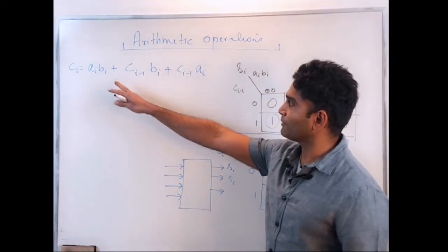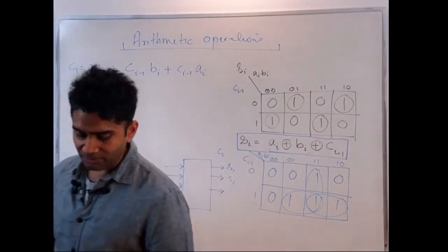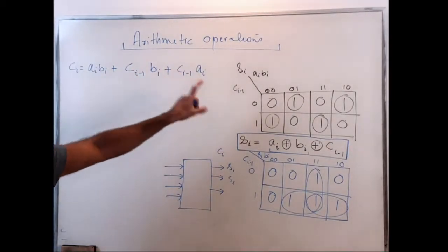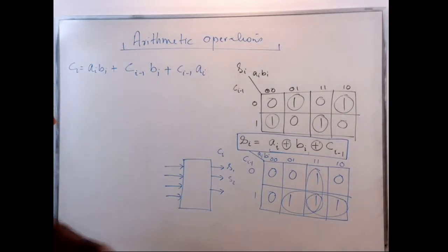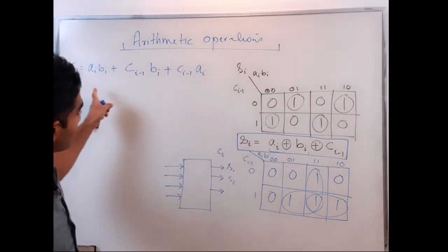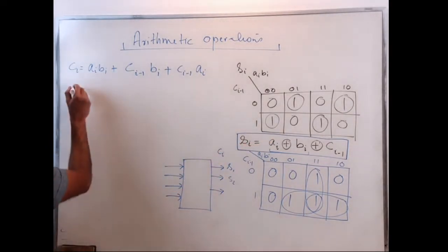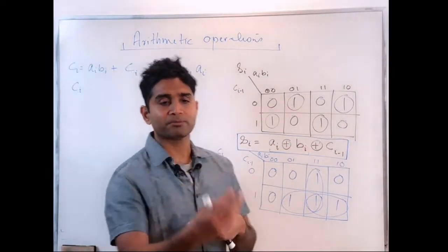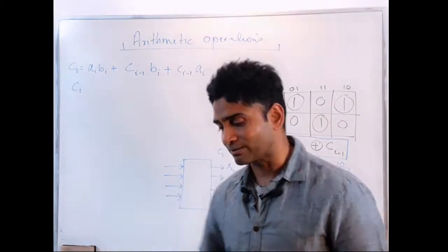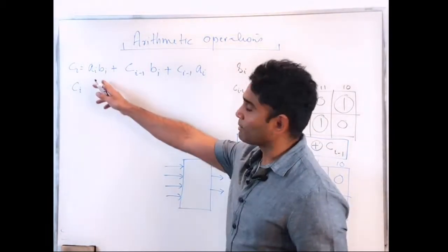No doubt that if I were to design a circuit with a single output, that would be the simplest circuit I can design using fundamental gates. However, because I have two outputs here, Si and Ci, if I can express Ci with some terms that are expressed in Si, then I don't have to re-implement some of the additional terms of Ci.